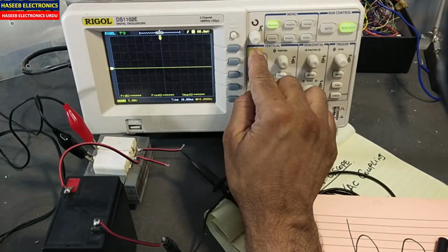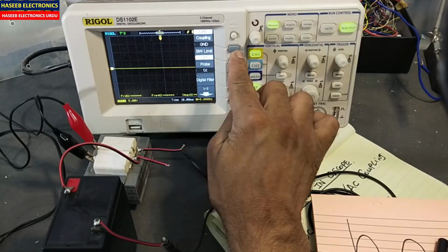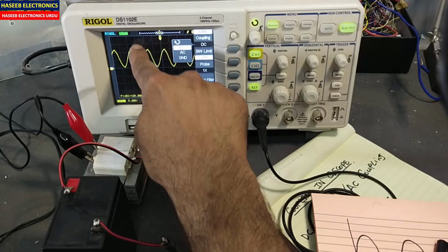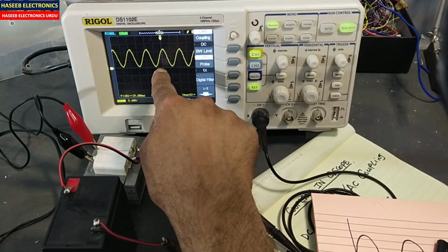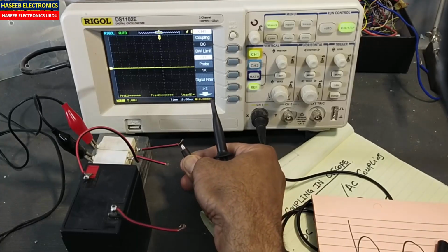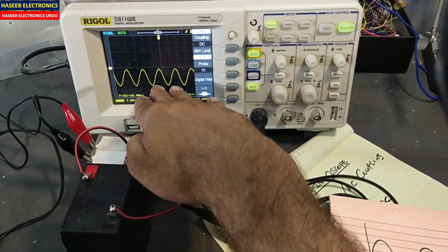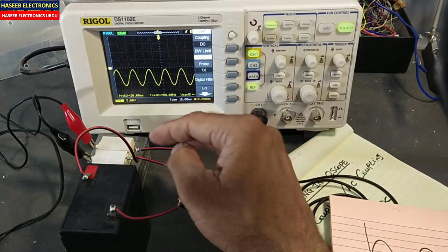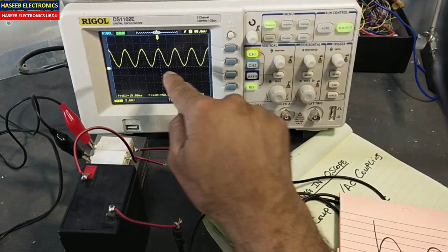Let's see again. Now connected to ground, nothing is displayed on the display. Connect to DC. This time the signal is elevated from the zero line. That means it has an offset with positive voltage. We have a positive voltage offset. Okay, if I connect in reverse, at that time I am giving the negative signal. So the signal is now in the bottom area. That means a negative offset is present there. Either it is negative offset or positive offset, it will transfer to the display.